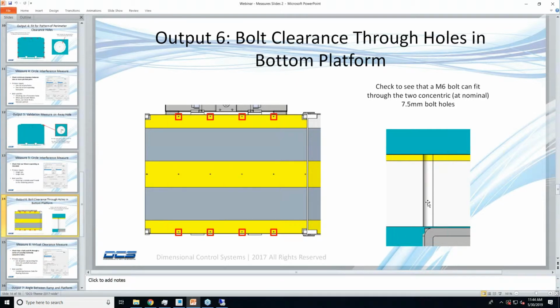But this hole is much longer, and so there's a much higher chance that the location of this top spot is different from the location of this bottom spot. And if I want to make sure that this bolt is going to pass through all 3 of these holes and probably end up being torqued down so its face is being pressed against this, maybe I want to check 2 spots of the same hole. So that's all I wanted to show you with this one: I'm checking 1 point at the center of this top yellow panel, and then 2 points to represent that whole axis, so that if there is some angular variation there, I am trying to take it into account.